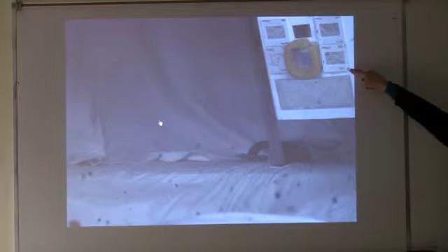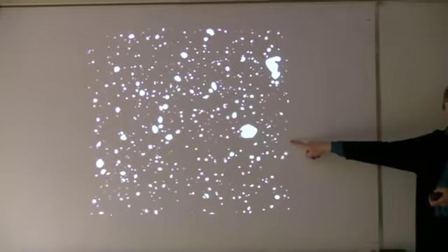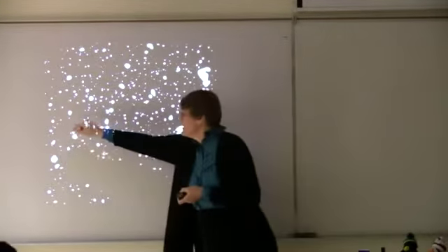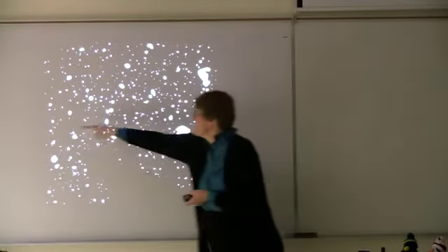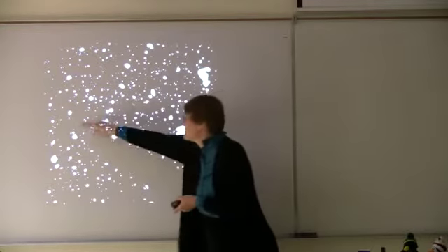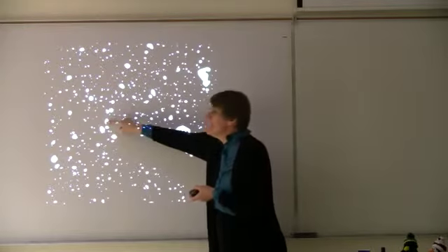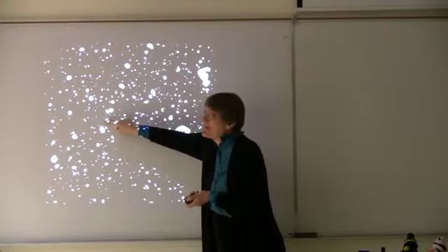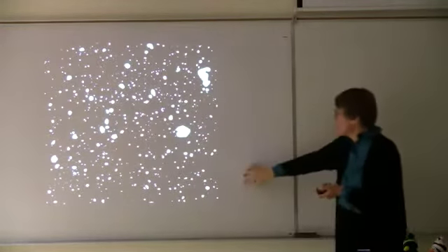So we take the foil back to the lab and scan it into the computer, and this is what the data looks like. NIH Image has an option where you click a button and it will measure every single particle on the screen. It basically rasters a computer beam across. When it hits a change in intensity, it travels around that object and reports the diameter for that object. So we can measure diameters for all these particles.